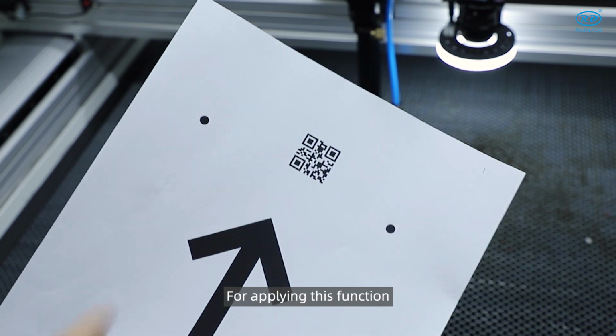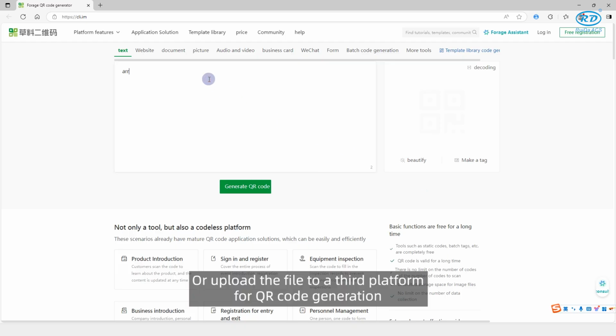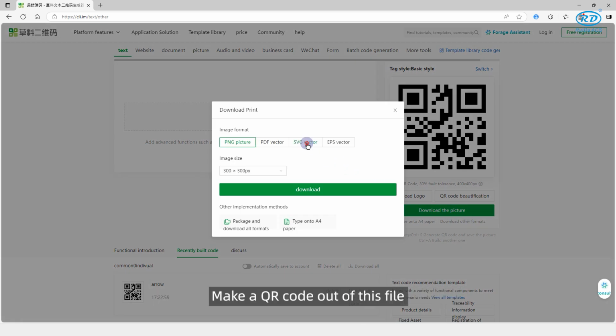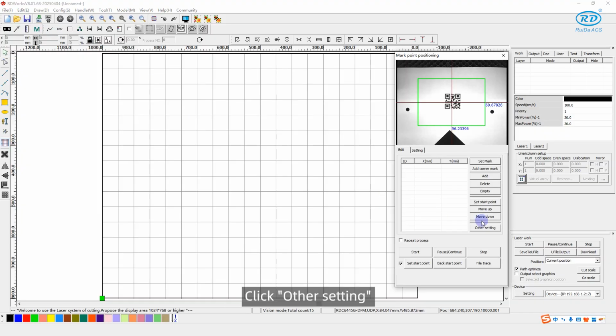For applying this function, a QR code is required on the material. Use the built-in QR code function in graphics software, or upload the file to a third platform for QR code generation. Take Arrow the processing file as an example. Make a QR code out of this file, and then print it on the material surface. In Mark Point Positioning, click Other Settings.